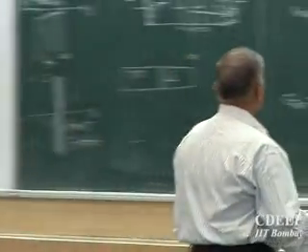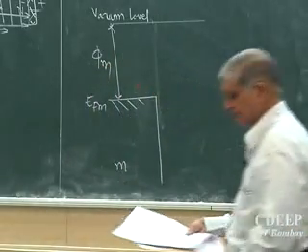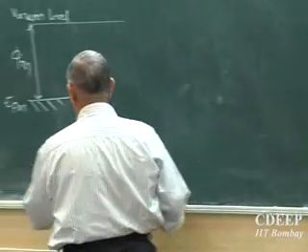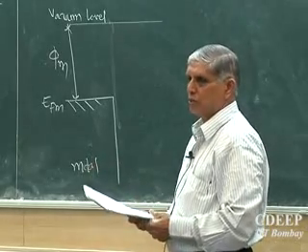In vacuum it is done so that the mean free path will be larger, and all atoms will actually hit here, otherwise they will scatter. So all the materials are deposited in vacuum. The energy where we assume the electron will come out is called the vacuum level. So it is arbitrary in that sense. This value is called the metal work function. Is it clear? The energy for an electron to leave the metal and go to free space is called the work function.